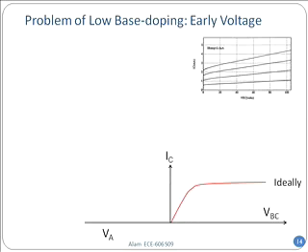So ideally, this is the flat characteristic you're supposed to have, but experimental data is on the top, and what you see, and what I exaggerate, is that in practice, the collector current, even at large VBC, keeps on increasing, and this is because of this depletion issue. So let's see how it works out. By the way, do you see the problem here? First of all, physically, forget about the math.